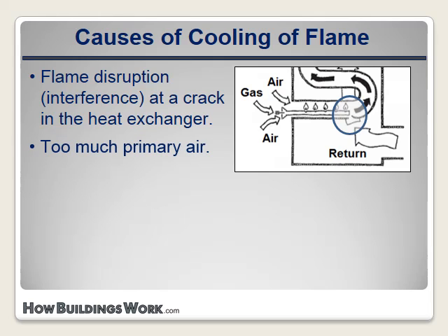It may at first seem counterintuitive that too much air would result in carbon monoxide production, but it can happen. The air that enters the burner is cool, so if there's far too much of it, it can force the fuel-air mixture to flow through the burner too quickly and cool off before the components have a chance to complete the combustion reaction and form carbon dioxide.